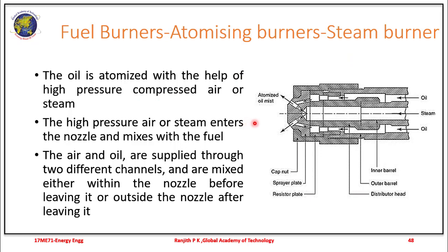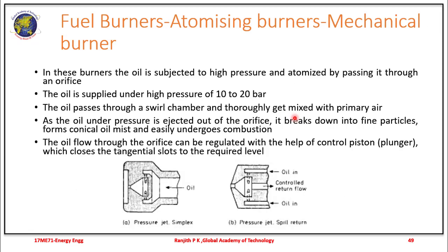And in case of atomizing burners, the steam burners, the high pressure air or usually steam is made to enter through the nozzle here, and this mixes with the oil that is passed here in this orifice. The air and oil which is supplied to different channels are mixed, and then it is allowed to pass to the further process.